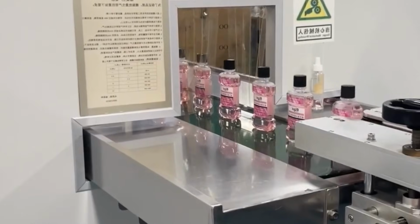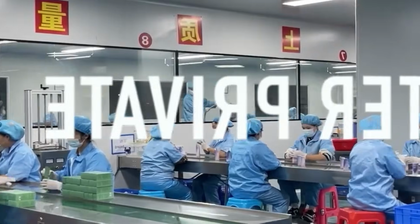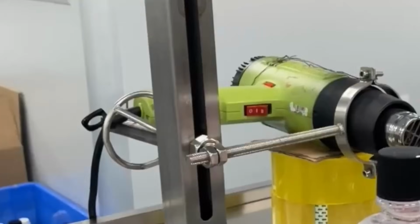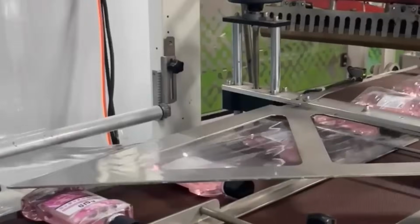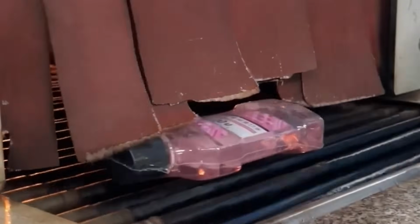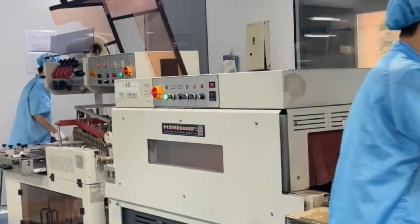Bottling begins with automatic bottle unscramblers that orient and feed empty bottles onto the production conveyor. Bottles are conveyed under a rinsing station where filtered air or ozonated water is sprayed into each bottle via nozzle inserts. Rinse nozzles retract after each cycle, and residual rinse is removed using vacuum-assisted drainage. Clean bottles move to the filling carousel.